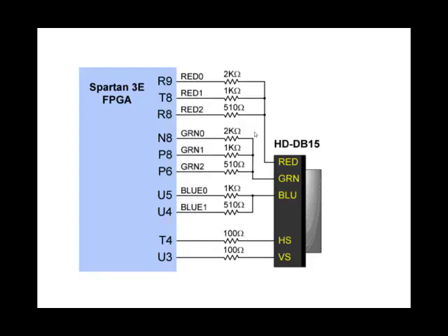3 digital signals are provided for red, allowing you to create 8 different voltage levels for the red. 3 different digital signals are provided for green, allowing 8 voltage levels for green. And 2 signals are provided for blue, allowing for 4 voltage levels for blue. With 8 digital signals for color, you can create 256 custom colors by mixing the red, green, and blue.